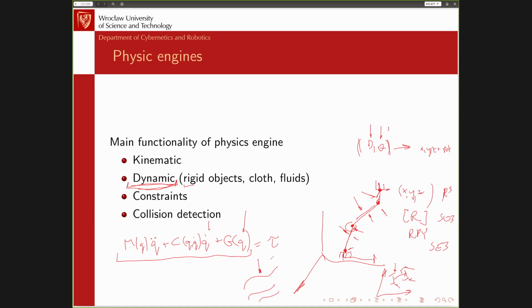This is needed when you design the robot. You have some masses of the links. You know the maximal accelerations and velocities, and you look for the motors which you need to put in the robot to be able to move along those trajectories, or with those accelerations and velocities.